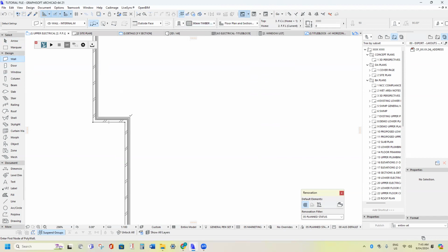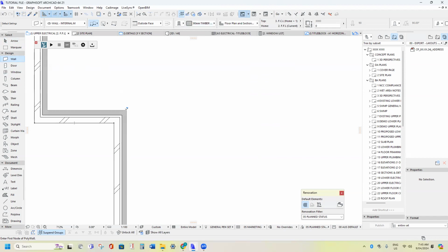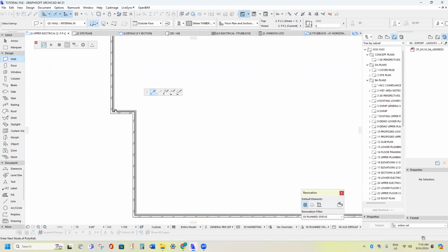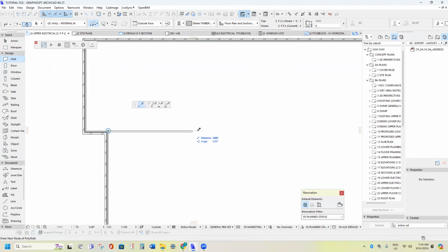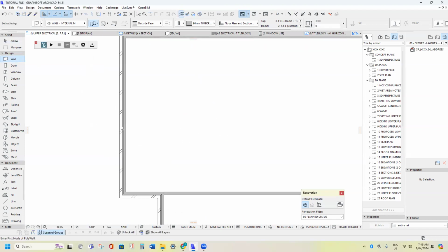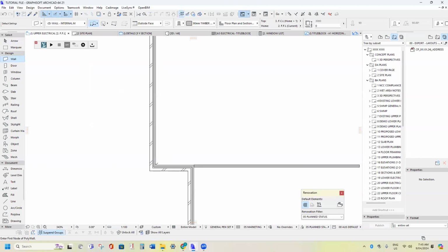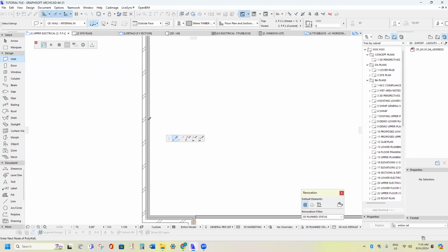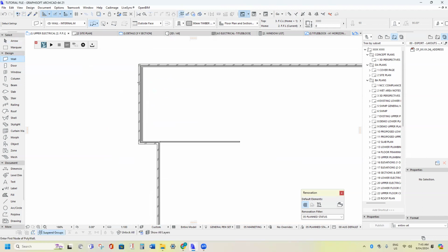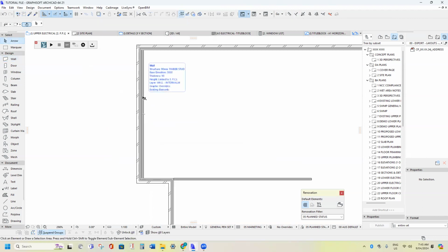I zoom in to this point. On the corner, see there's a tick there, then you know that it's on the corner. And you click and straight away it's on the wrong side. So I'm going to go up to this and click that. Then I'm going to hold the Shift key down and take it back to just a random spot there and double click, because I need to get the length of the garage here, which I haven't got yet, which will be 6 meters. So I'll draw a straight wall against there, double click, and press escape.